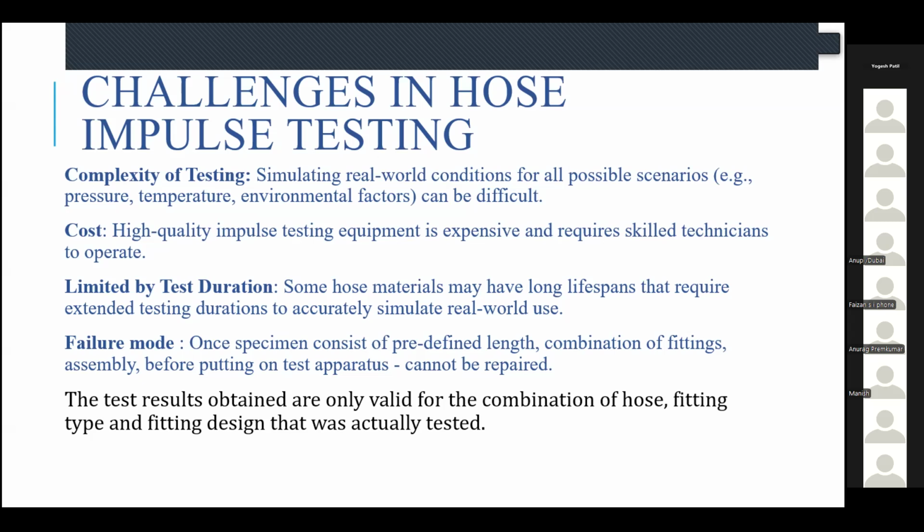One needs to be very precautionary and clear that this whole set of specimens needs to be intact with respect to the requirement. That is where we face challenges: sometimes the fitting is procured, but the fitting combination with respect to hoses is not selected properly, and that is basically the main failure mode by which hoses fail.